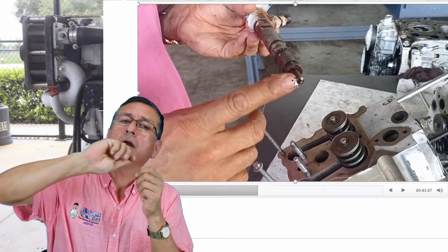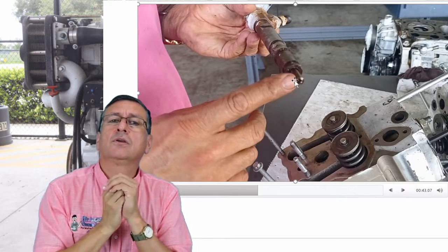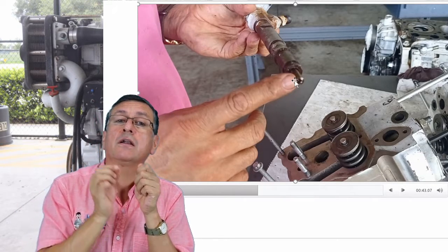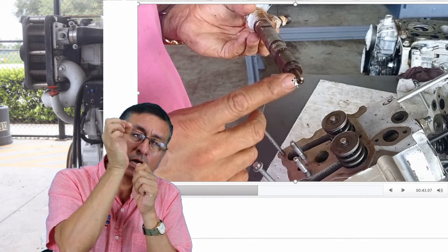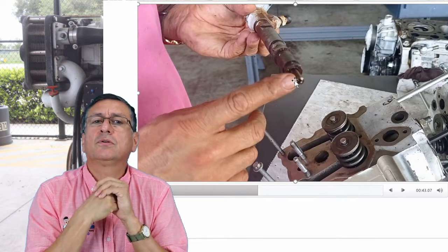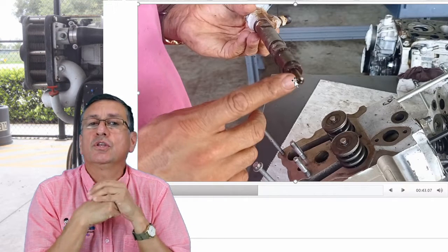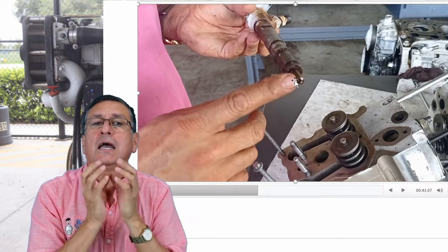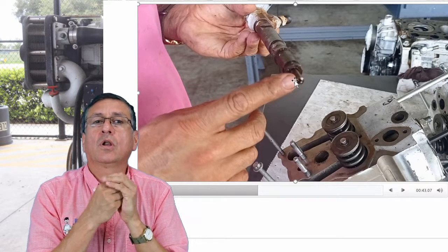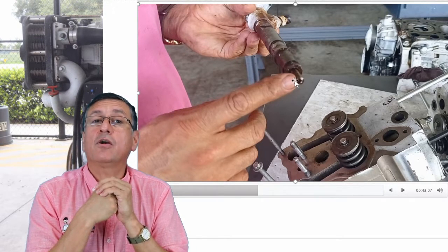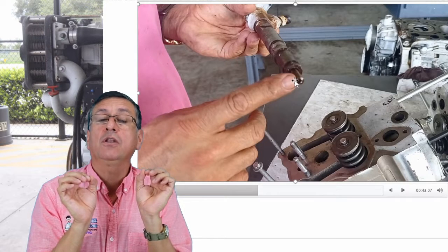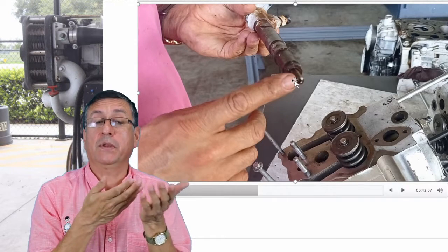If you have a wire brush, clean the nozzle, and if you have a magnifier and a needle, try to clean the holes on the nozzle in order to verify that those holes are in good condition. If the holes are a little eroded or a little melted, I recommend you order the kit for the nozzles and replace the nozzles. I'm going to explain right now the procedure.